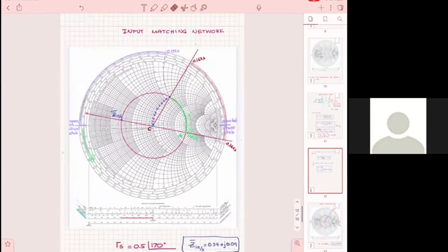Now, I also have to tell you that on the Smith chart, because a full movement around the Smith chart is half a wavelength, the result from moving from A to B and the result from moving from A in the opposite direction to B, electrically, even if the length may be different, electrically you have the same result in terms of matching.